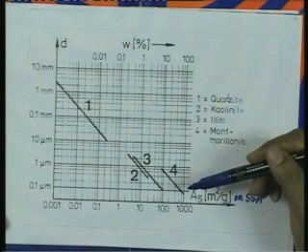So, in addition to this, we also saw clay and water interactions and also defined adsorbed water and cation exchange capacity. We also said that with increase in specific surface area, there will be an increase in the cation exchange capacity. Now, having seen about clay and water interaction, let us look into the soil structure or soil fabric, which is nothing but arrangement of the soil particles relative to each other.